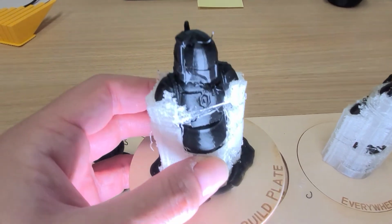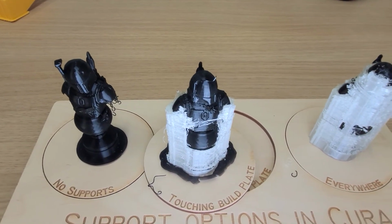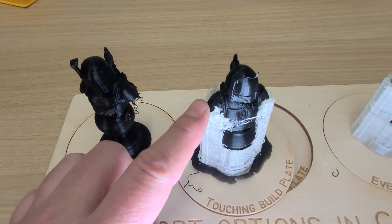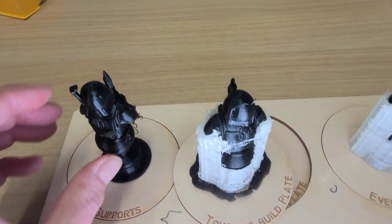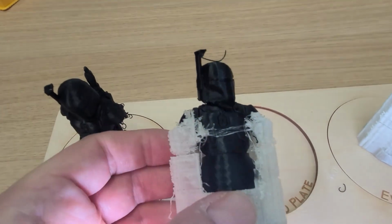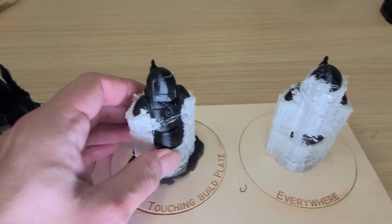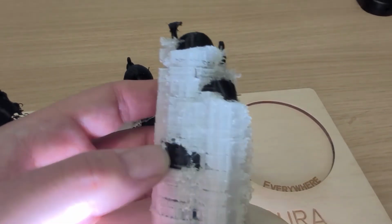Okay, touching the build plate, so this will only print supports where it needs it from the point down to the build plate, so it won't do any overhangs that are kind of intermeshed with the actual piece, and you can kind of see it there on his chin there. It hasn't done any because it doesn't touch the build plate, and everywhere it does what it says on the tin.